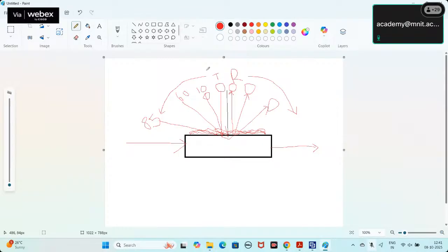And if you are putting your transmitting antenna at 90 degree, then the incident signal will not directly meet with this surface. Okay, that's why I am telling you the 90 degree of theta is not possible in the case of absorber. And the placing of your transmitting and receiving antenna is in this manner. Okay.